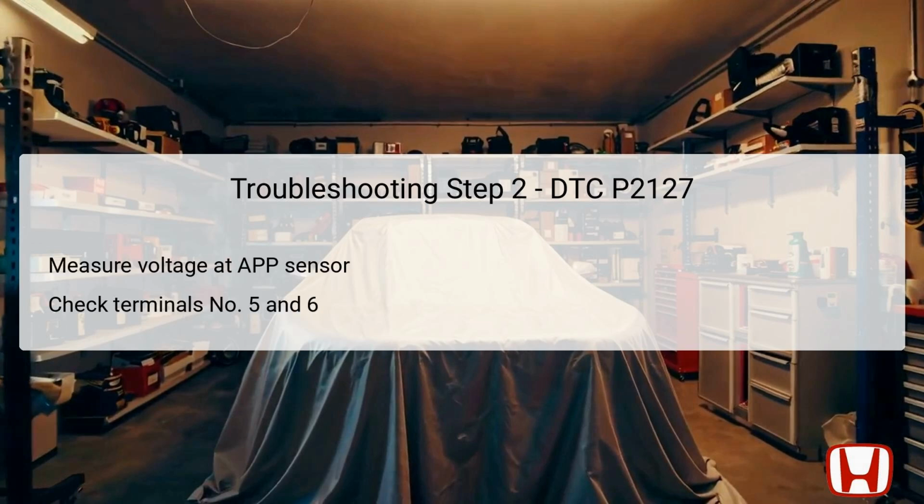In the second troubleshooting step, the technician must turn the ignition switch to the lock position, which is the off state. Following this, the APP sensor 6P connector needs to be disconnected for further analysis. With the ignition back in the on position, it's necessary to measure the voltage between terminals number 5, SG5, light blue wire, and number 6, VCC, gray wire, of the APP sensor 6P connector.